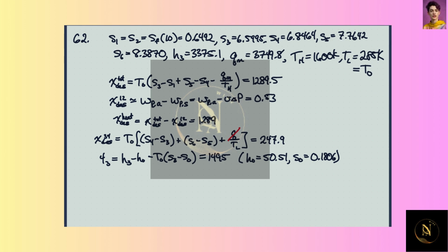And this should be a prime here, because in this case we didn't have a perfectly efficient pump or an isentropic pump. Then we can go back and get the entropy at the various points in the process that we calculated before. Some of these we can get from problem 37, because we know there were some efficiencies in the turbine.